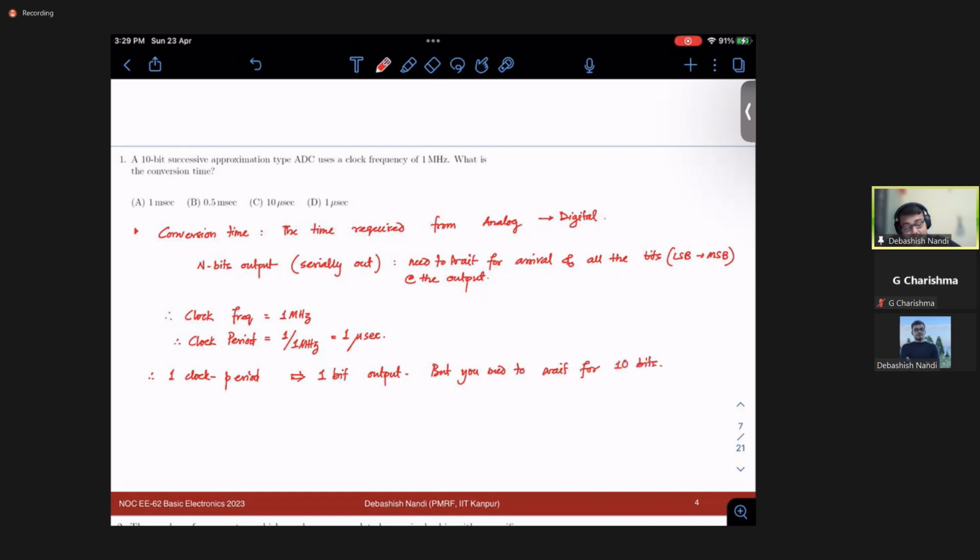So what will be your net conversion time? It is nothing but 10 into 1 microsecond, because you have a 10-bit output. So your conversion time would be 10 microseconds. Fine. So your answer would be C.